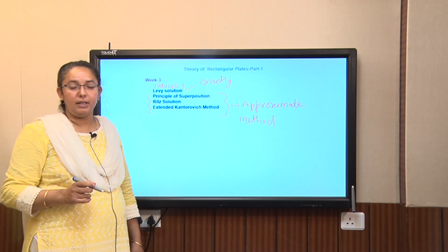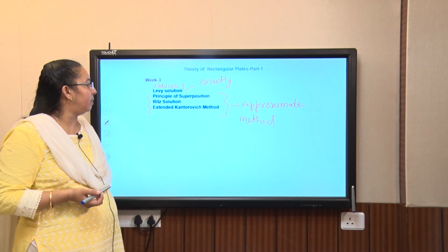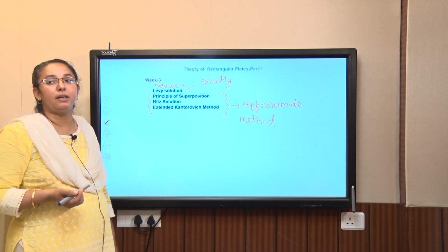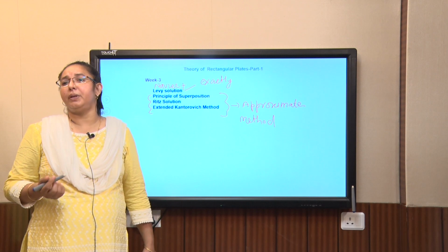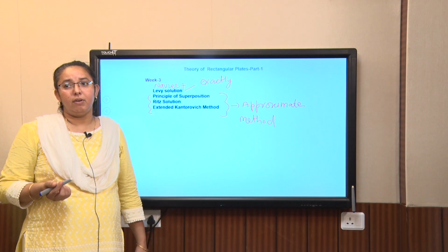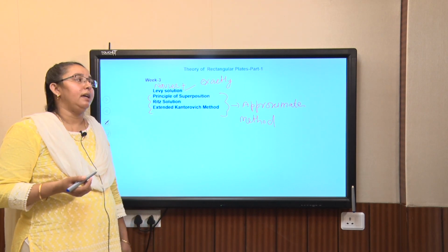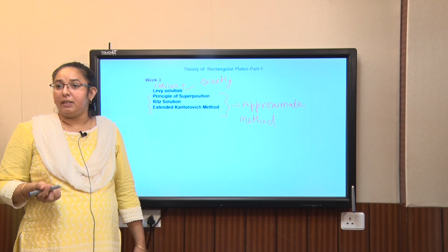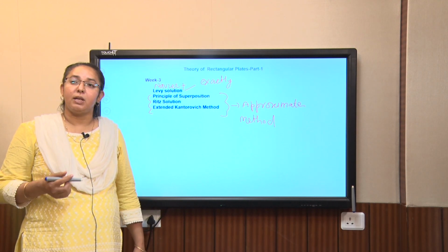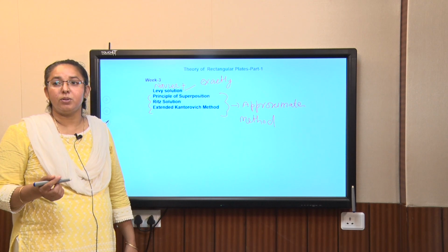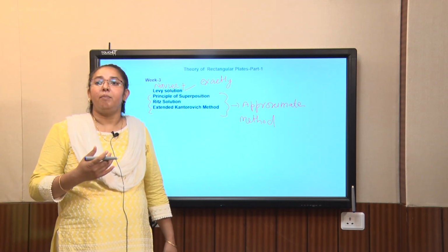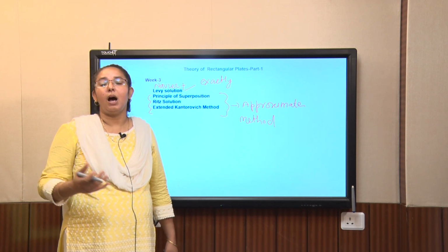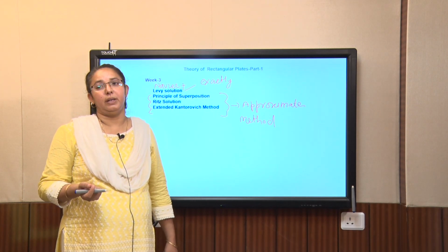Approximate methods are preferred, out of which the principle of superposition, Ridge solution or extended Kantorovich-Ridge method. These days some new techniques have also been developed, like the asymptotic method, the symplectic approach or some other techniques, which are also used to develop approximate solutions when a plate is subjected to arbitrary boundary conditions or loadings.